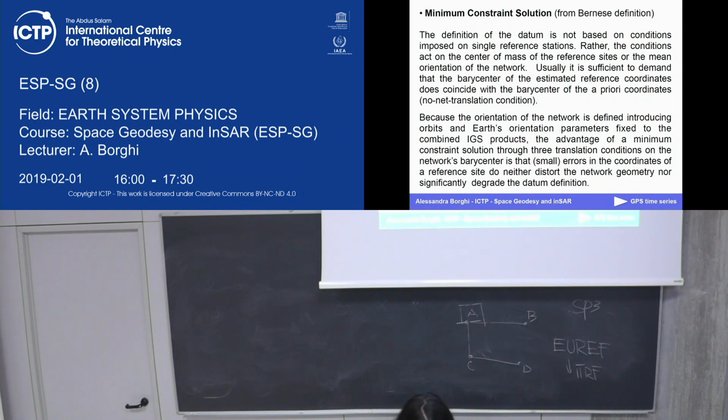And at the end, you check, using a Helmert transformation with 7 parameters, rotation, translation, and scale, if your solution is in agreement with the theoretical solution. Of course, we don't obtain the exact values, but you can control, for a day, if you have a problem at station A, which is a reference station, and that day this station doesn't work well, for instance because it is on a mountain and is covered by snow.